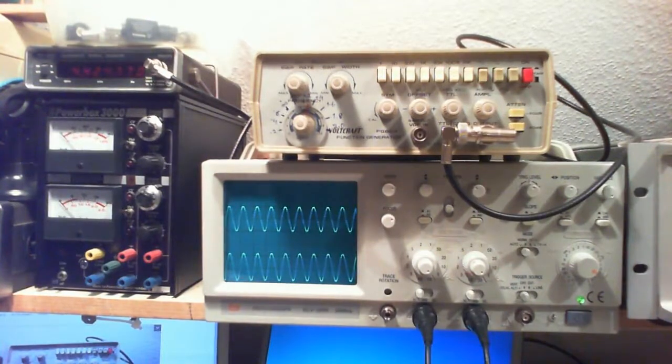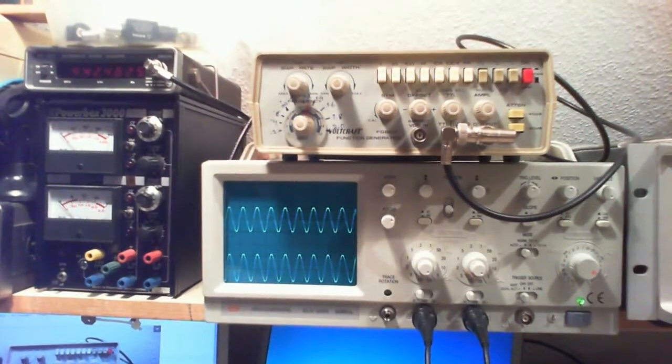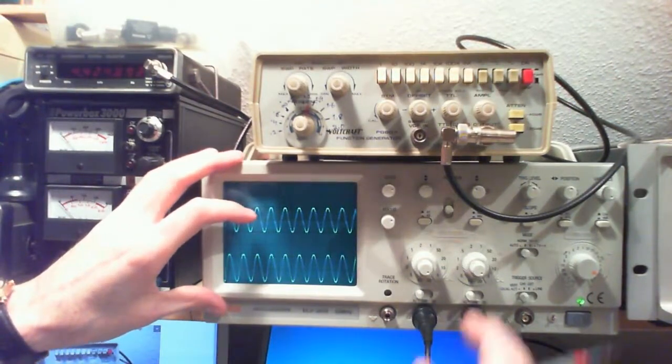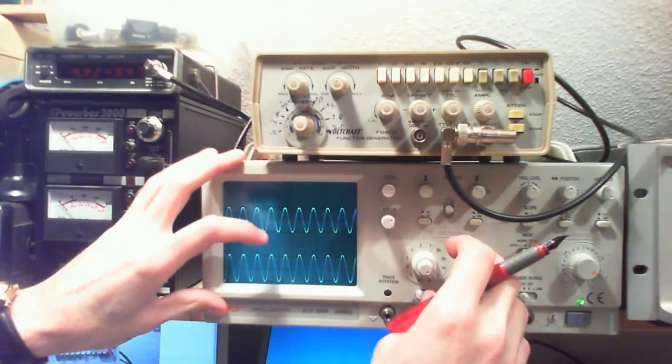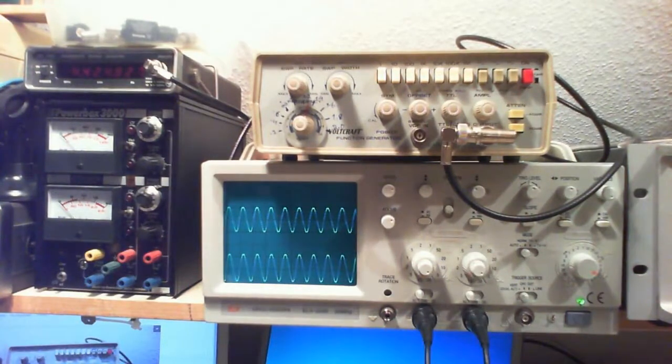At this frequency, my input is, let's take the input as it is, at 20 volts peak to peak, and the previous output I want to take as it was, so I take it as 20 volts and 10 volts. I don't want to mess with the data. So at 4.76 megahertz, the input is at 20 volts peak to peak. The output is at 2.2 times 10, which is equal to 11 volts peak to peak, and that's the peak.